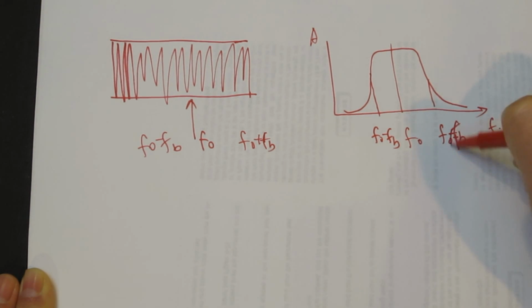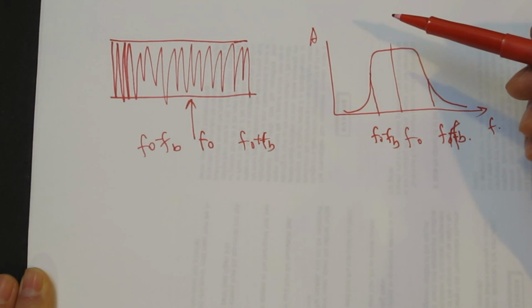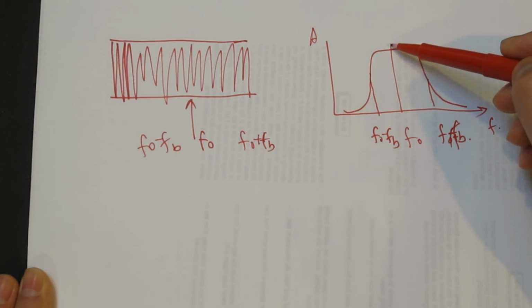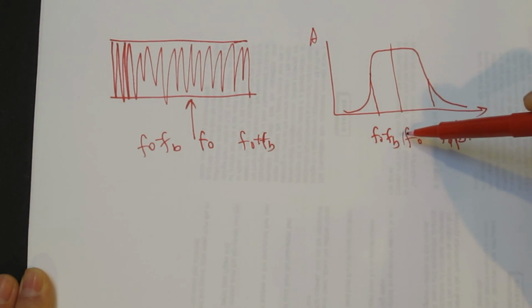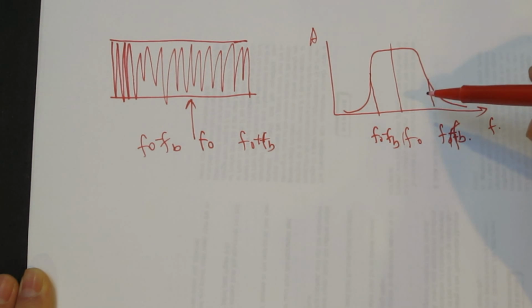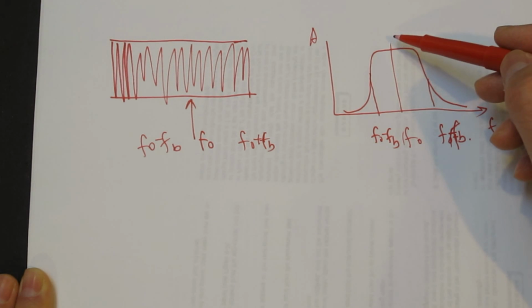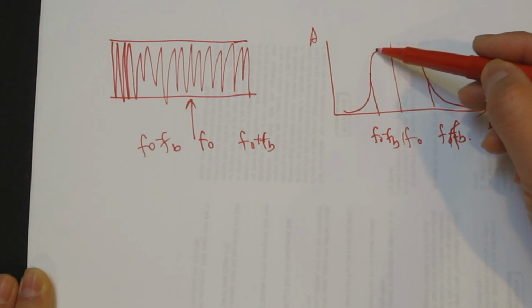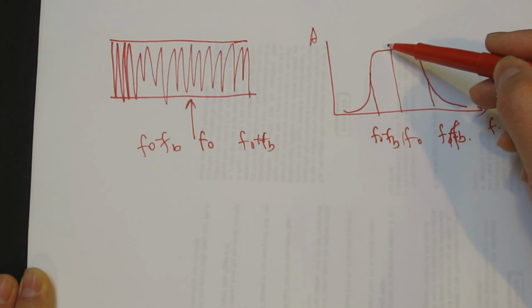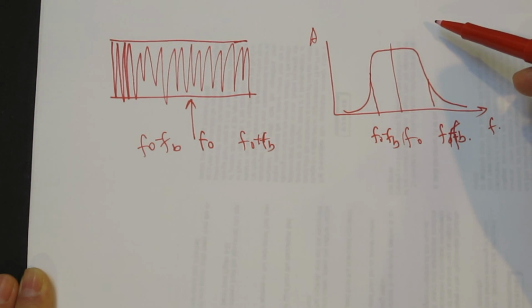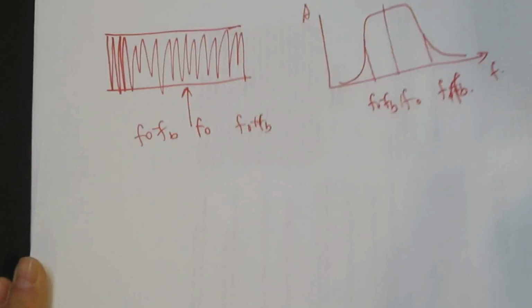As you can see, if we use the same technique as with the AM signal, sitting on F0 with our zero span on the spectrum analyzer, we are not going to see much, because as the frequency shifts, we get the same amplitude. The amplitude is going to be a straight line, so we can't demodulate our signal. Well, or could we? As it turns out, we could.